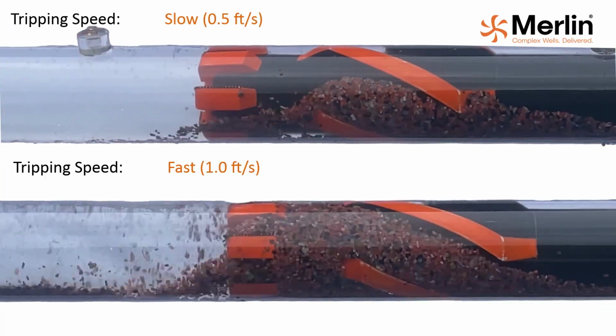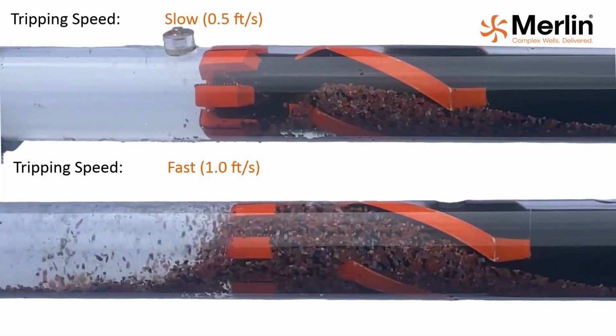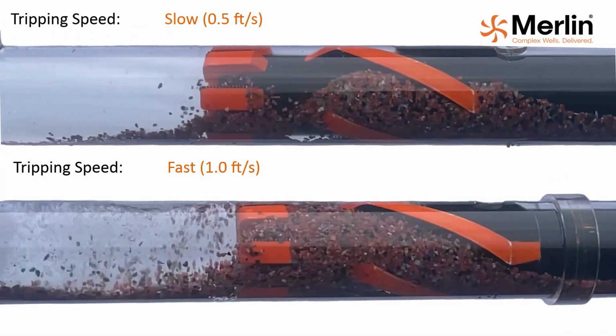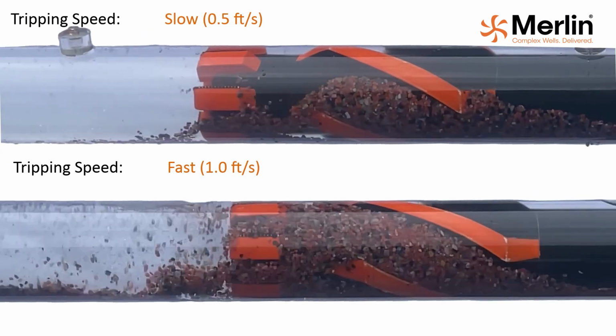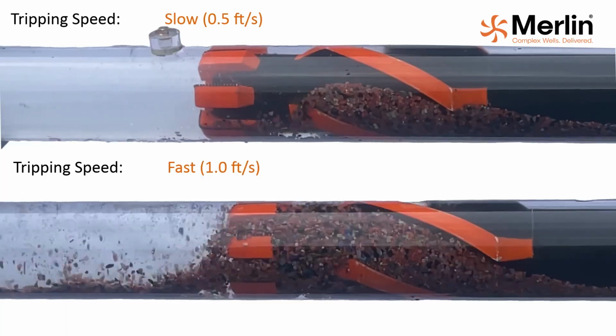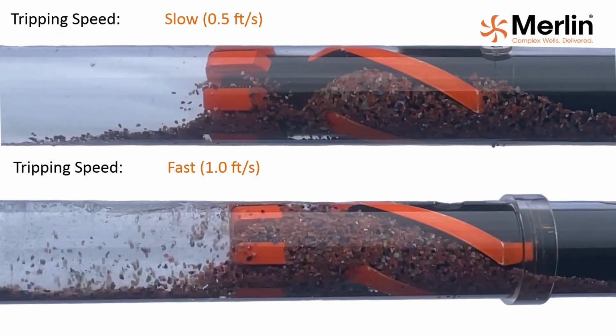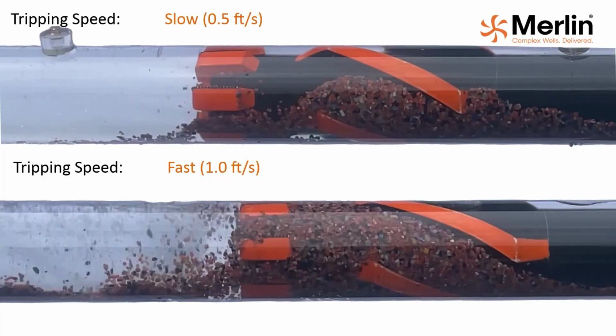Another problem with pulling fast is it gives less time to react if something goes wrong downhole, possibly exacerbating problems. In the bottom simulation, the pulling speed is high enough that the fluid velocity, along with the low viscosity of water, generates turbulent flow, which can be helpful in pack-off avoidance. This will not always be the case with drilling fluids, however.